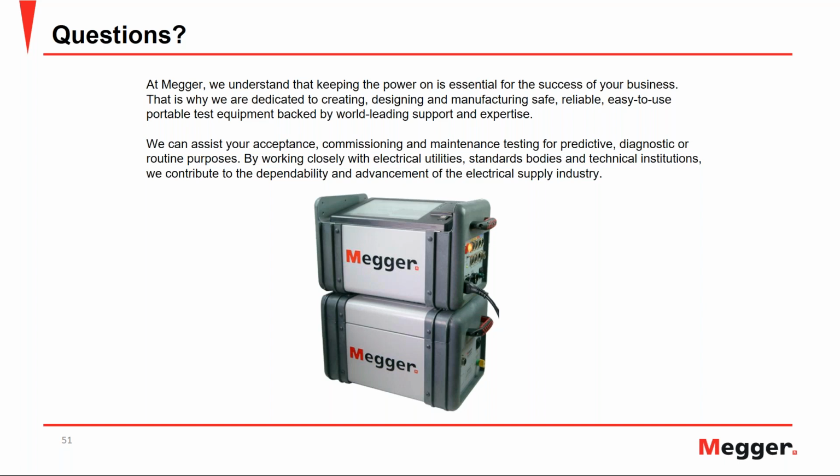So that's the way it determines it, and it's just based on your 60 hertz, because you can do a voltage dependence factor even if you're not performing a narrowband dielectric frequency response. So it just monitors the harmonics of the signal, and basically just compares the weight of those harmonics to its fundamental. And if there are too many harmonics in that measurement, then that's where your voltage dependence factor will flag.